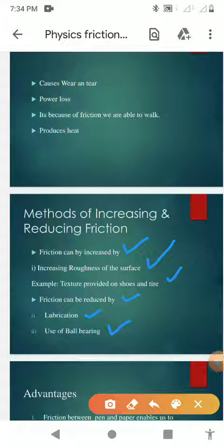Most of the time we have often seen that if our fan is creating irritable noise, which is quite irritating, then when the electrician opens our fan and you observe the bearing, the balls get destructed, or there is a pitting kind of failure inside the ball. It means the ball gets damaged because of this continuous friction, and hence we can provide a new bearing so that noise will not be generated.